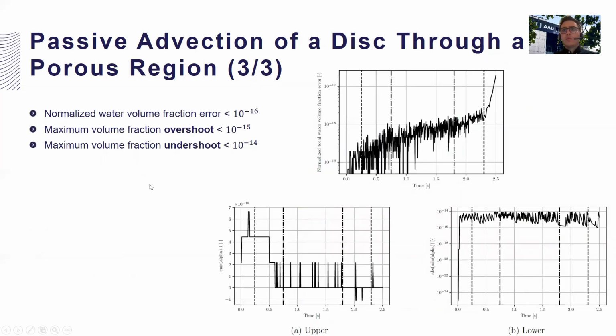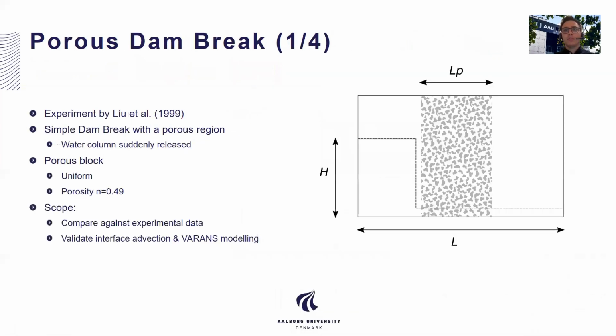In this slide, we'll see some quantitative results related to the volume fraction conservation and boundedness of our new development. It is clear that the volume is conserved excellently with errors that stay below machine precision, while the bounding of the algorithm is also outstanding since again, we observe values close to the machine precision. This was a reasonable result since the base method that is extended during the study, namely isoAdvector, has well-documented conservation and bounding properties.